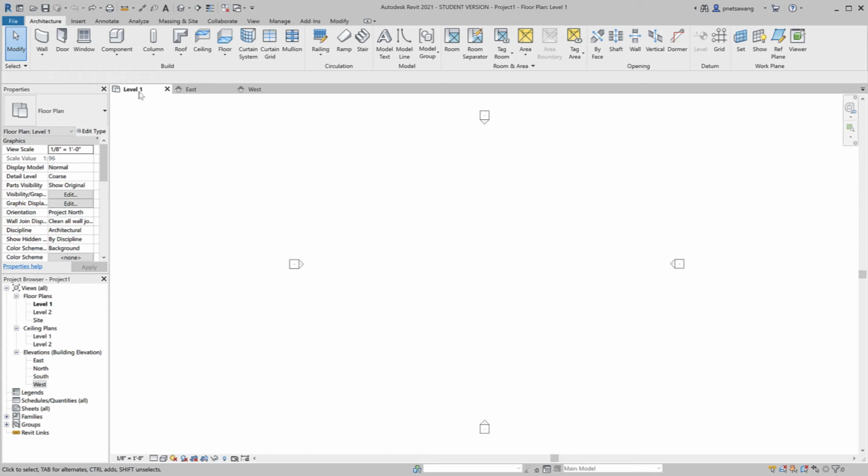You may ask, instead of undoing it, why don't I just delete all those 5 grids? As I mentioned before, Revit keeps a running number in the background. So if I delete those 5 grids, then the next grid that I place after that is going to start with grid line number 6. Now you can rename that grid line number 6 to start with 1 again, and it'll reset the count. So it's really no big deal. It's just a matter of preference.